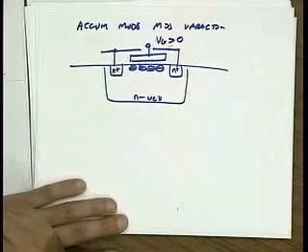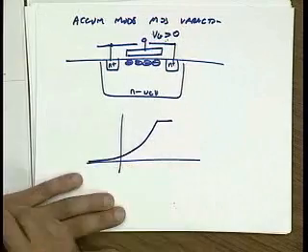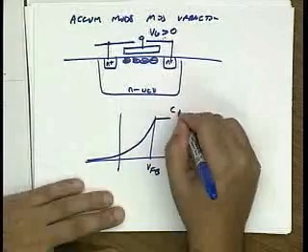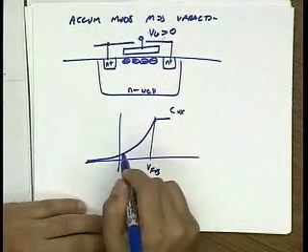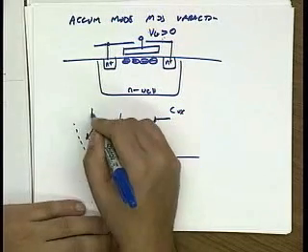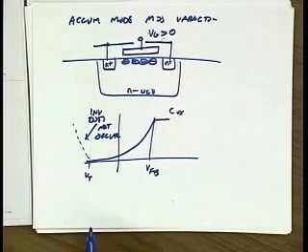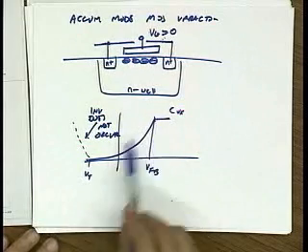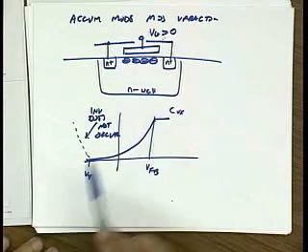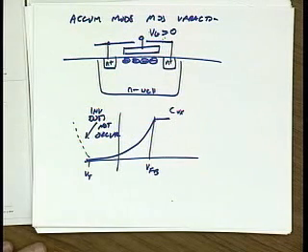And now we can actually get a device whose curve looks something like this. So this is the flat band voltage, this is Cox, and basically inversion does not happen. And that's nice because that means that the capacitance is monotonic versus control voltage. So I can go from 0 all the way to flat band and get a nice monotonic response. Okay? Questions? Comments?